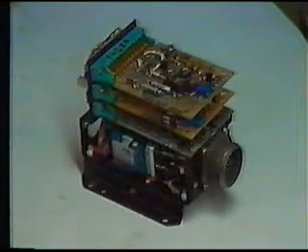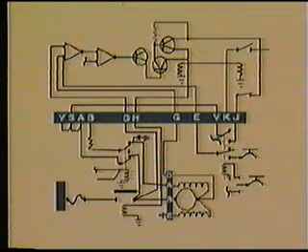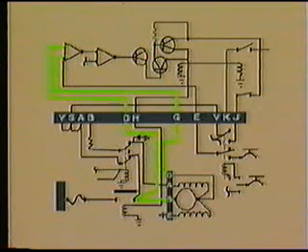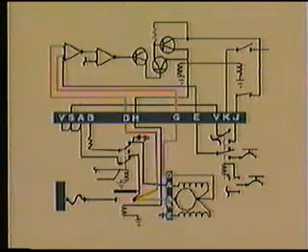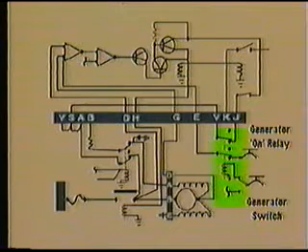Now let's look at some of the internal details of the control panel circuitry. Here is the auto line contactor circuit. The action starts here with a device called an operational amplifier. Inputs to this device are provided by the B and D leads of the generator. The control panel uses this flow as one of the factors to determine that the output of the generator is not reversed. When the generator switch is moved to the on position, the generator on relay closes.